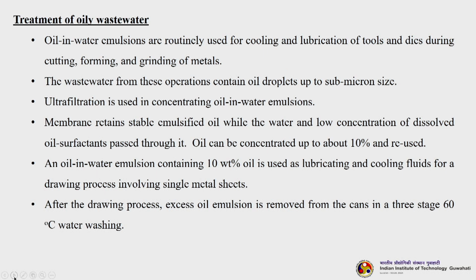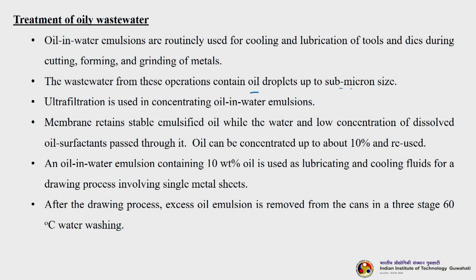Now, the next application is oily wastewater. So, this is one of the most significant applications of ultrafiltration. Oil in water emulsions are routinely used for cooling and lubricating of tools and dies during cutting, forming and grinding of metals, mostly in refineries, then near metallurgical industries and other process industries of course. The wastewater from these operations contains oil droplets down to submicron size.